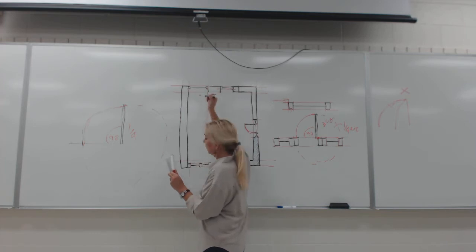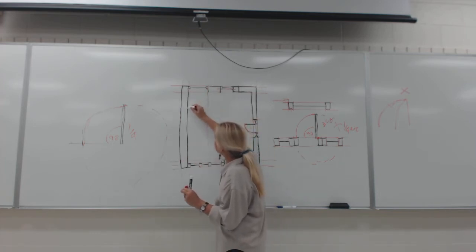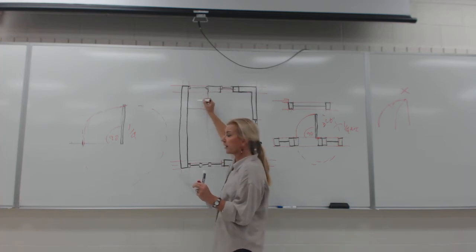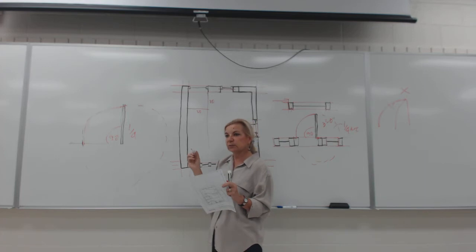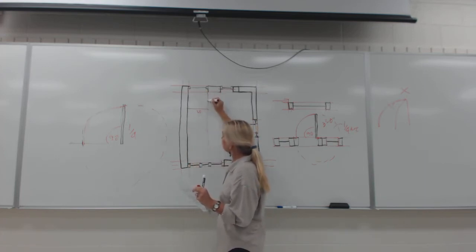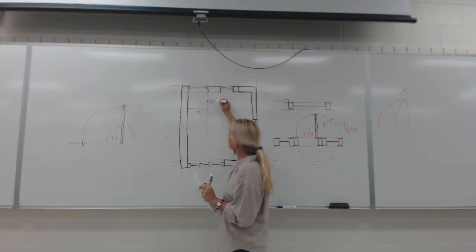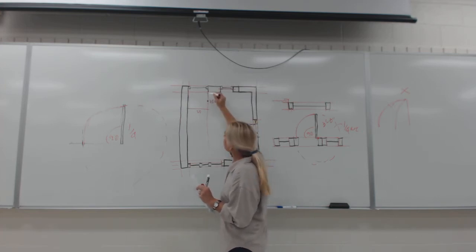So we have a window at the bottom, and just so you understand, the stair starts with a square. So this is 30 inch and this is 30 inch. It starts with the square because stairs actually start here. So in the middle, we're going to place a dot, and we're going to say up, small up. And this is already first riser.